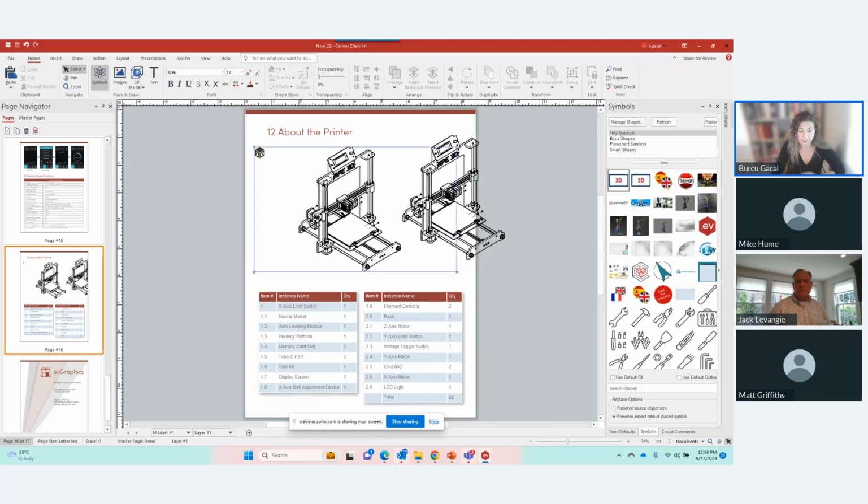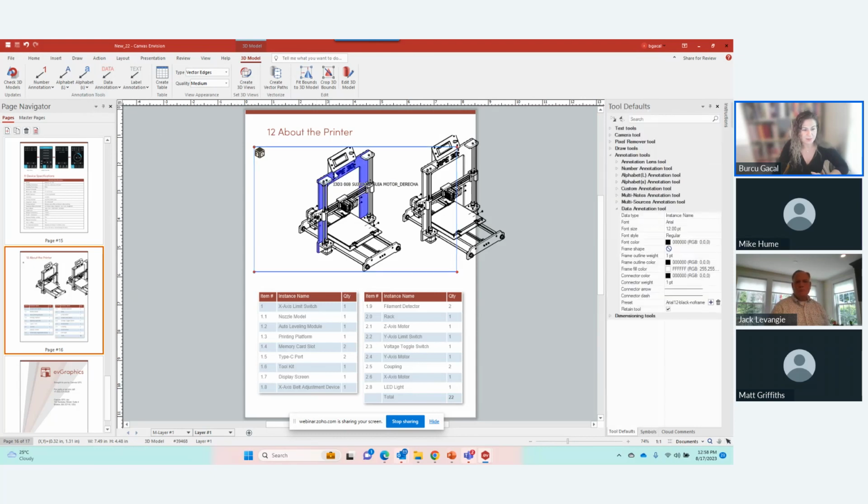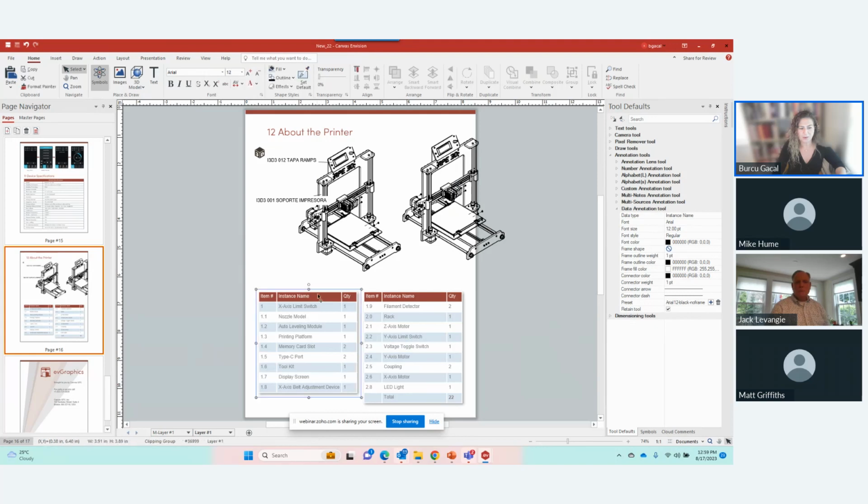The one on the left-hand side is still a 3D linked rendered image, and I can simply annotate parts in here. As you can see, when I move my cursor, it's still tied into the bill of materials, so I can annotate the parts and simply create these cool part lists. These part lists can be modified and worked on inside of Envision, bringing in data from spreadsheets and enriching the content as well.